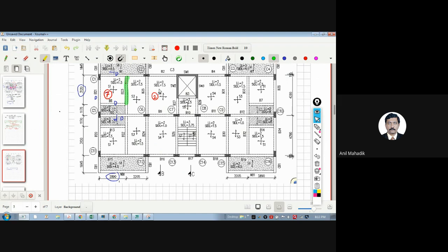This is also continuous because in S4 it was continuous, meaning in S3 it is there. That's why we have taken that. So this is my continuous. Is this continuous? Yes, sir. Horizontal one? Yes, it is also continuous. Is this continuous? No, sir, because there is sunken slab, so it is discontinuous. Now here also it is continuous in this zone, green zone, but here actually there is a discontinuity.